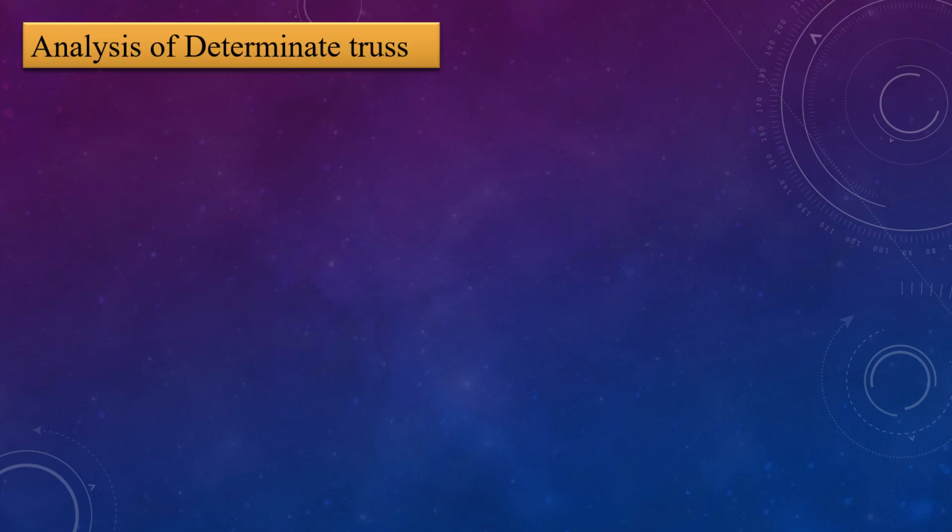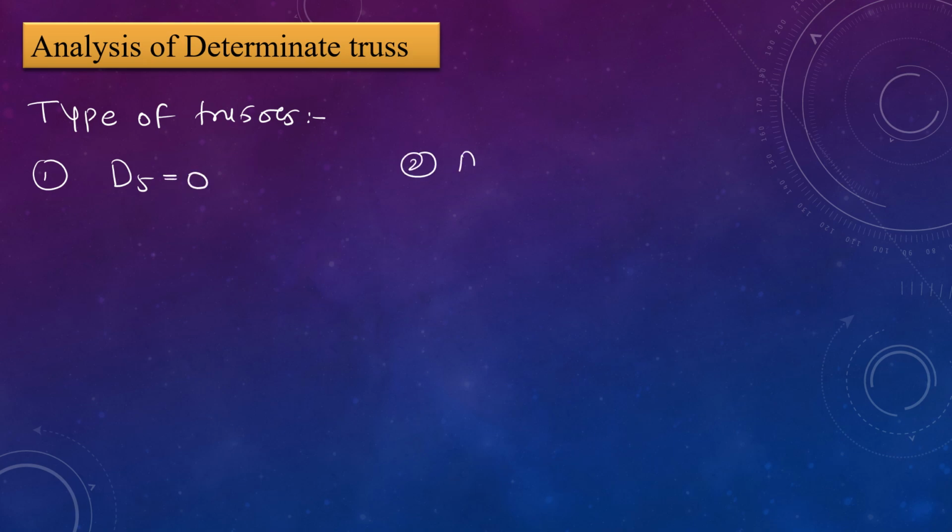So here is the analysis of determinate structure. First, in case of analysis of determinate structure, we'll discuss the types of trusses. There are three types of trusses: perfect truss, redundant truss, and deficient truss. First condition, if ds value, meaning static indeterminacy, is equal to 0. Second, if ds is greater than 0. And third condition is if ds is less than 0. There are three conditions.